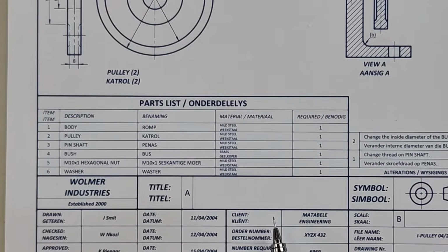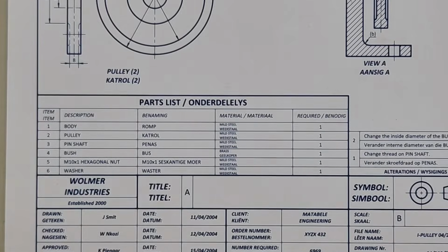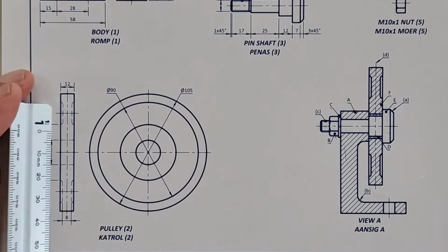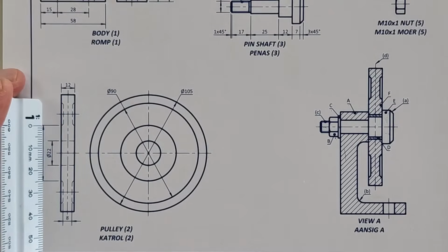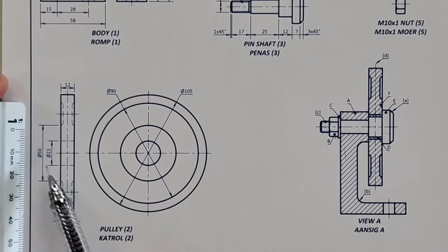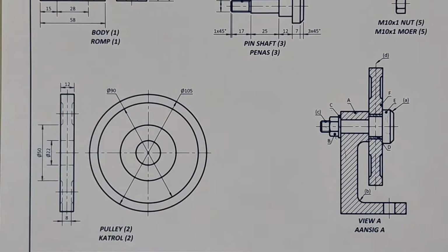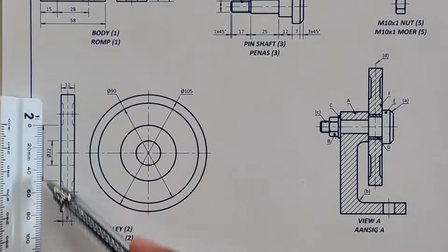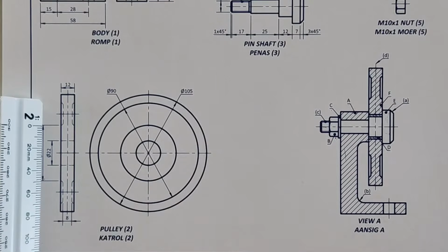So to do that, you're going to use your ruler, and you'll have to find a measurement here. Now, if I go down here, there's a 50, that's at 25. So if I measure the actual measurement, it's 25 millimeters. If I read it, it says 50. So what scale am I using here? 1 to 2. It's half scale. And to double check that, take your half scale, and you'll see that on scale 1 to 2, it corresponds with the 50 on that one.